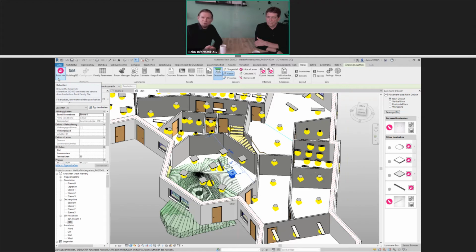You can take any luminaire, you can create your own luminaires in Revit quite easily. Just make a box, call it luminaire, and attach any IES file to it, and then you have your luminaire created, your generic luminaire by yourself. And this also can be used with our plugin in terms of calculations, of transferring to ReluxDesktop, back and forth and so on.